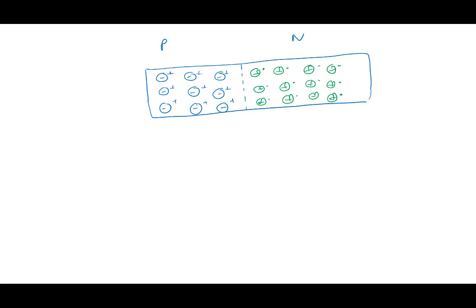Electrons here, negative, let's add negative charge here. So what's going to happen now? Let's say we just managed to put both of them together, n-type and p-type, right? What will happen? Two things. One thing you have to remember: this is immobile. The arsenic is bonded with silicon here and silicon here. This is not going to move.